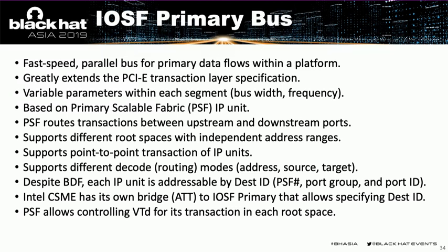We have found that the Intel Converged Security and Management Engine has a special, very privileged bridge to the IOSF primary bus, operating on destination IDs and issuing point-to-point transactions. Also, we have found that PSF allows to control VT-d or IOMMU for devices connected to its ports.